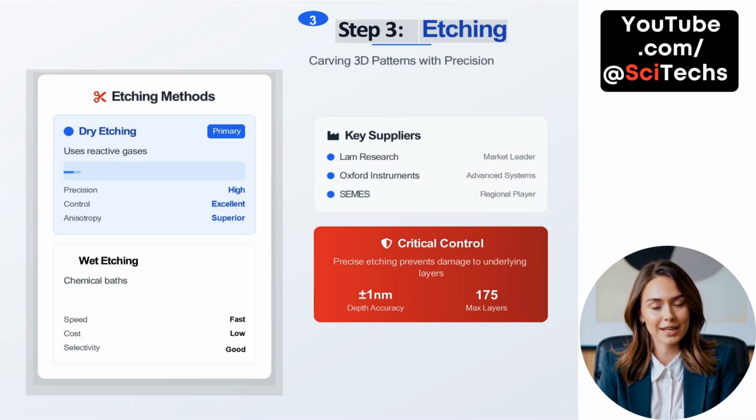Critical control during etching is essential to avoid damaging underlying layers, especially with devices stacking up to 175 layers. Etch depth accuracy must be within plus or minus 1 nanometer. Key suppliers include Lam Research, the market leader, Oxford Instruments, offering advanced systems, and Semis, a regional player. Each contributes to meeting the demanding standards of today's complex semiconductor architectures.